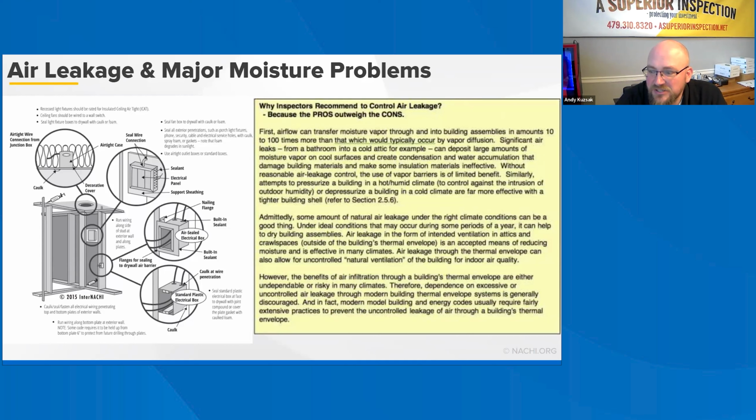Reducing air leakage is essential, and air barrier systems aim to block leaks while addressing rainwater protection and vapor retarders. Effective air barrier materials include gypsum wallboard, spray polyurethane foams, wood structural panels, foam boards, and building wraps. Seams in these materials must be sealed to ensure low air permeability.